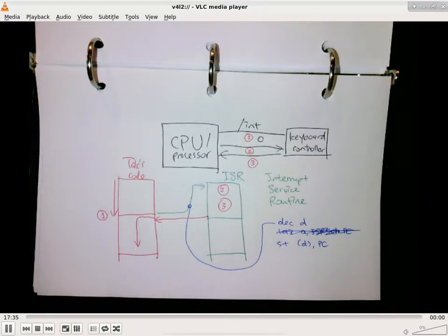So are we saying the ISR does access the stack, but then it doesn't increment, decrement properly? Or is it just while it's doing that? Oh, okay, but while it's doing that, it could just mess up what's already on there? Yeah, exactly. So when the ISR executes, it can use the stack as if your code is using the stack. As long as the ISR keeps the stack pointer balanced, it's all good. So when it goes back to the code right there, it'll be at the same spot, but it could have messed up stuff below and above it. Just below. Oh, okay. Not above. So whatever the stack pointer is pointing to and whatever is above it is safe.